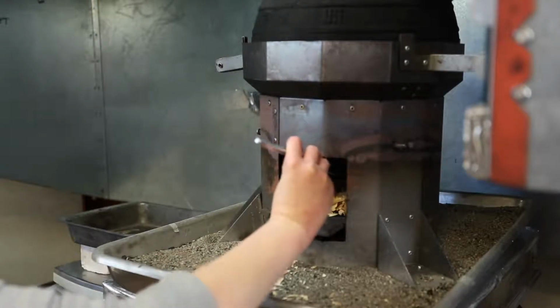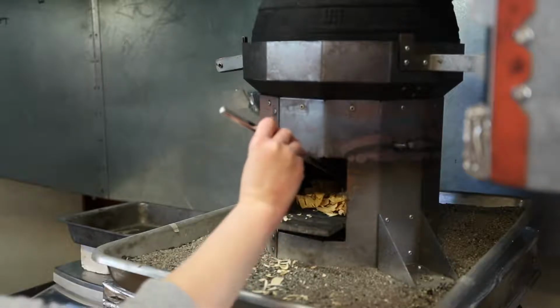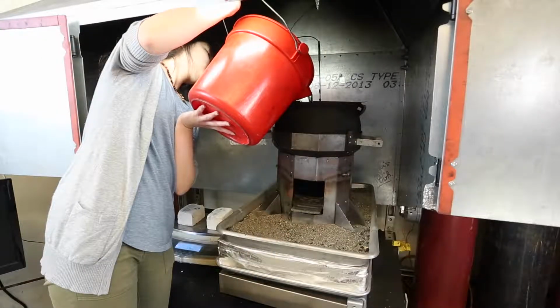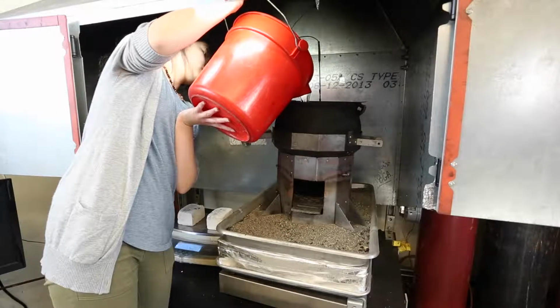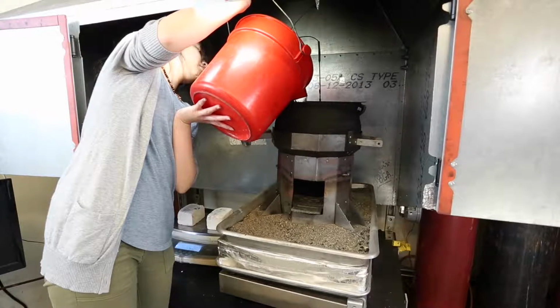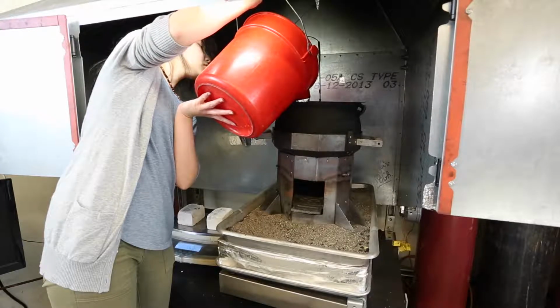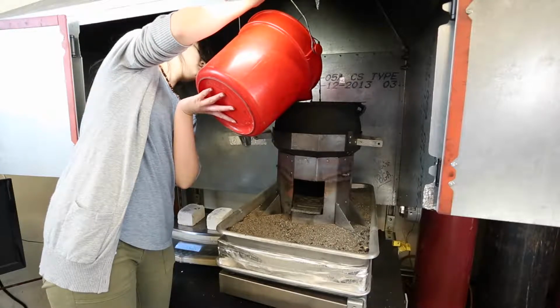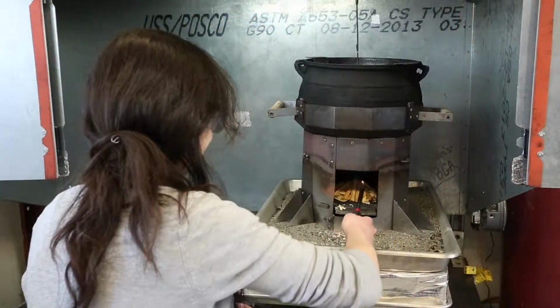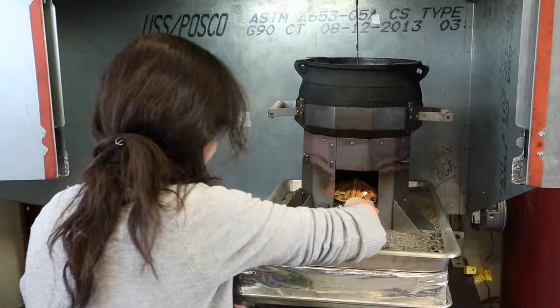Once the materials are gathered, we load the fire-starting materials inside the cookstove's firebox, followed by the pot, the 5 kilograms of water, and the thermocouple probe secured with a holder. We verify that the thermocouple's output, which at this moment represents the initial temperature of the water, is reasonable and logging continuously as appropriate. Finally, we start the fire with a lighter, signaling the start of the test sequence.